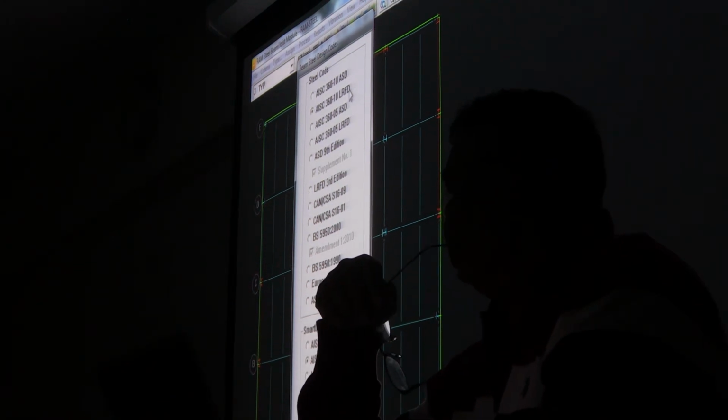It will not be changed that much, but if you download it today, you'll have that this should be AISC 360-15. Now, do you know where the code actually is in that book? The book gives you all the tables of the geometry, right? That's not the code. The code is actually chapter 16, the spec.